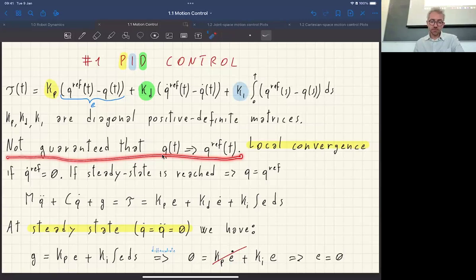which makes very much sense to me because you're not using any model information basically. So here the performance of the controller is entirely dependent on the three gains, Kp, Kd, Ki. So it depends on how good you are at tuning those gains. Okay, so it takes some experience to make this work. It's not too difficult. I've done it several times. And it does work pretty decently in practice, but again, it depends on which robot you're controlling, which motion you want to generate, what accuracy level you want to reach. But it can work in many situations, and it's quite common in industrial robots.